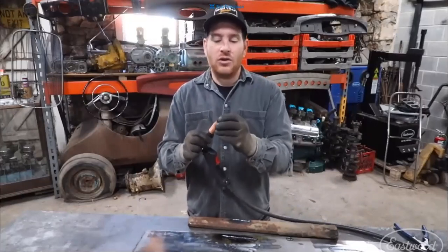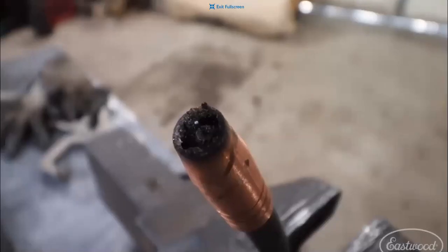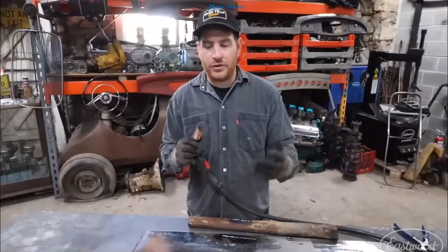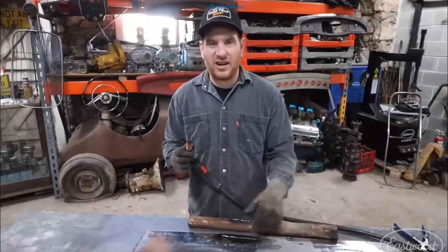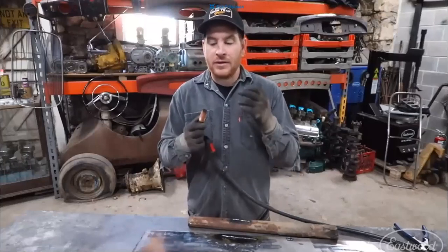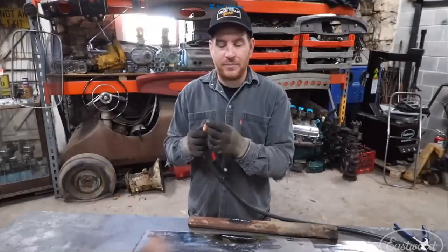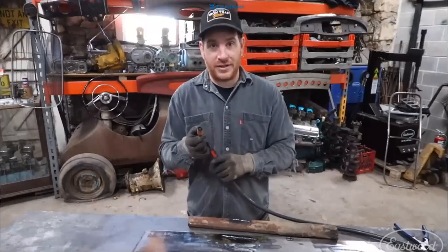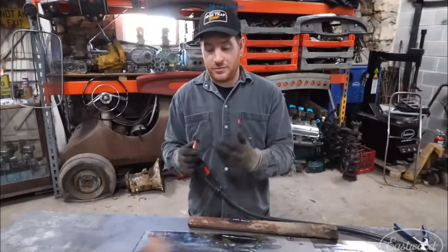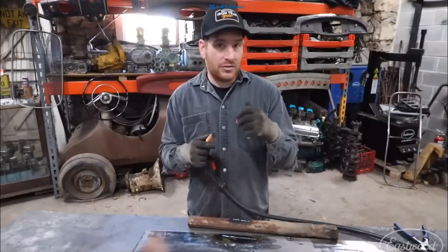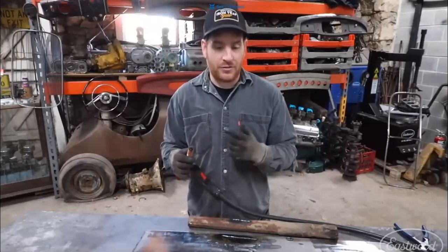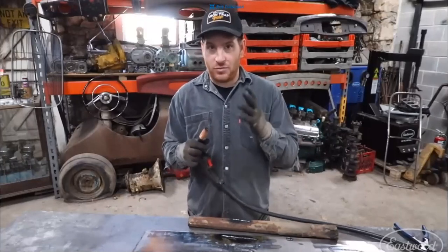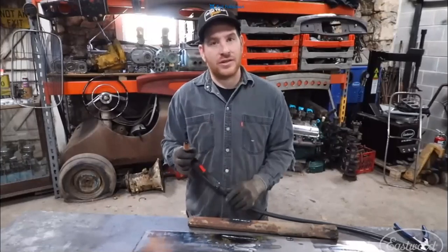sometimes my nozzle will actually get a bunch of buildup of spatter on the nozzle from welding. And you may be doing a ton of welding, you don't notice it. Next thing you know, you're getting porous welds or getting soot around the weld that gets dirty, check your nozzle or your consumables. Sometimes they get blocked up and it actually will block the shielding gas that's coming out of your MIG gun, and that could be causing your problem. So it could be as simple as just threading the nozzle off, cleaning it out on the inside, putting it back on, and you're up and running. So check one of those things, and usually one of those three or a combination will be what causes your problem. The number one reason MIG welds might suck.